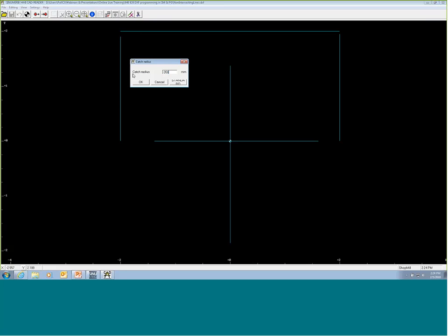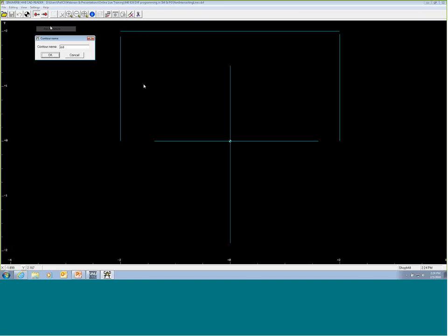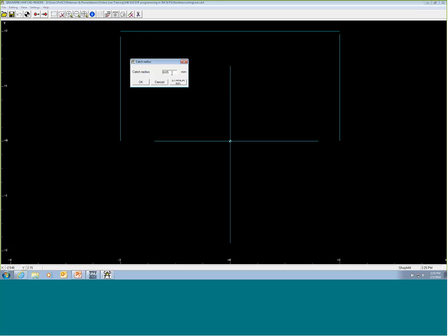So if I set it to, let's say, 50 thou, now as I start to pick different features, you'll see it doesn't let me pick these lines. So on the other side of the coin, if you have that value too small, you do have issues, and you'll find, hey, why can't it connect? But the scary part is if you put in a value way too large. So let's say, for argument's sake, I had a big value in there, maybe an inch. And now we start to pick features. Now you're going to see it gives us portions of an element that I might not want. This came all the way over to my center hashing, which was a big gap, because that gap was greater than the value. So just be careful, because this can certainly give you some pain points.